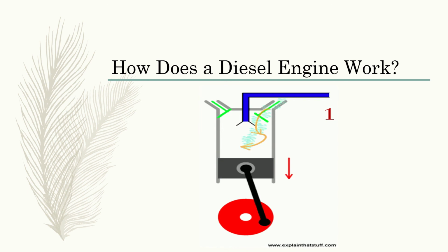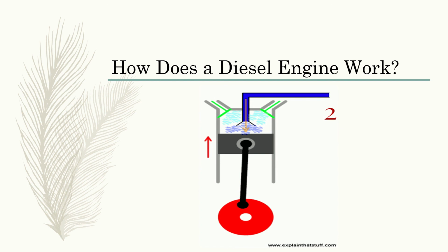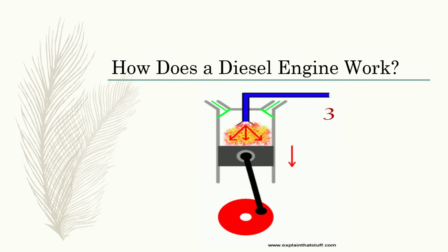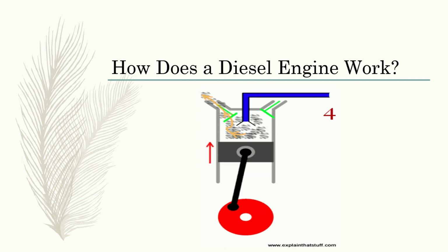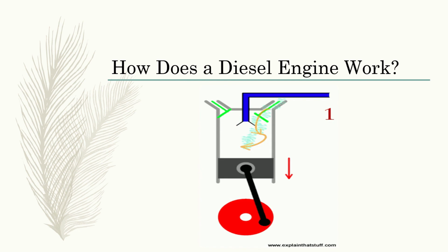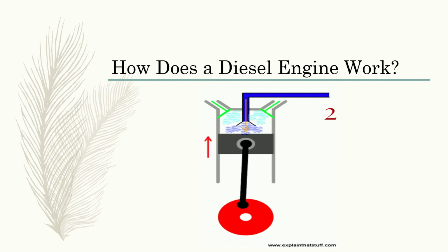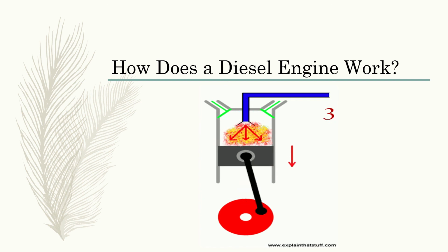It helps give better force, better power, and uniformity. In short, the more cylinders it has, the smoother it is. As an additional idea, a heavy flywheel is provided to smooth out the non-uniformity of the power.